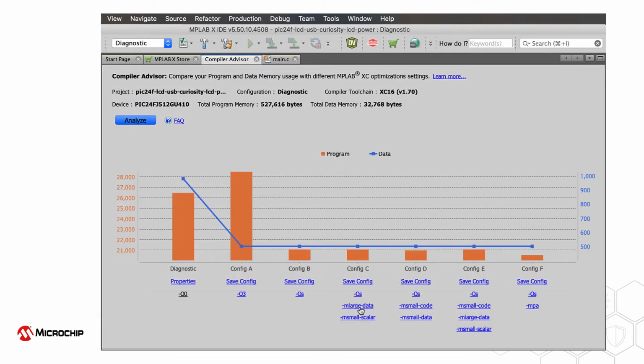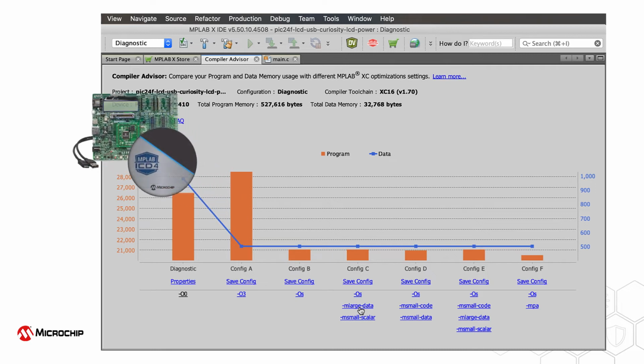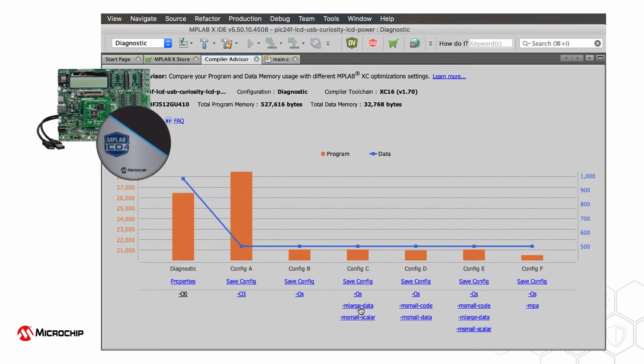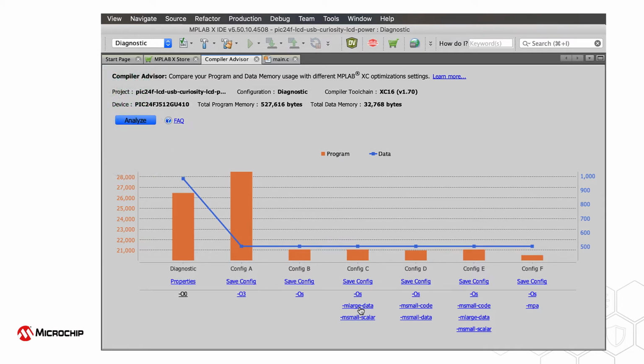In this analysis, we see typical results for a licensed compiler. The program size decreases with higher optimization levels, but increases when the speed-orientated Level 3 optimizations are employed. An assessment of a program's execution speed would need to be measured separately on your device hardware. The results for other device-specific options show that some work better than others for this particular project.